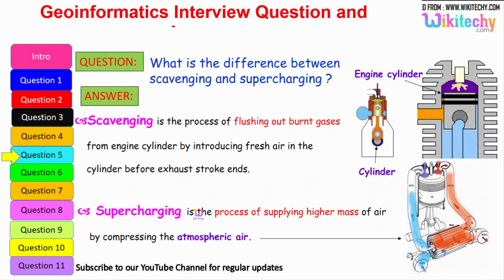Let's move on to the next question. What is the difference between scavenging and supercharging? Scavenging is the process of flushing out the burnt gases from the engine cylinder by introducing fresh air into the cylinder before the exhaust stroke ends.